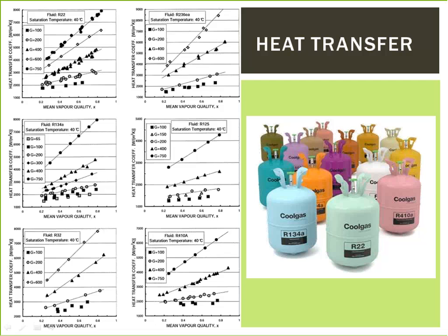Many factors affect heat transfer. Several have to do with the refrigeration system itself, such as piping design and material and flow rates. Three key properties of the refrigerant also affect the overall heat transfer capability of the system. These are viscosity, specific heat, and thermal conductivity. The factors are used in the design of the heat exchangers.